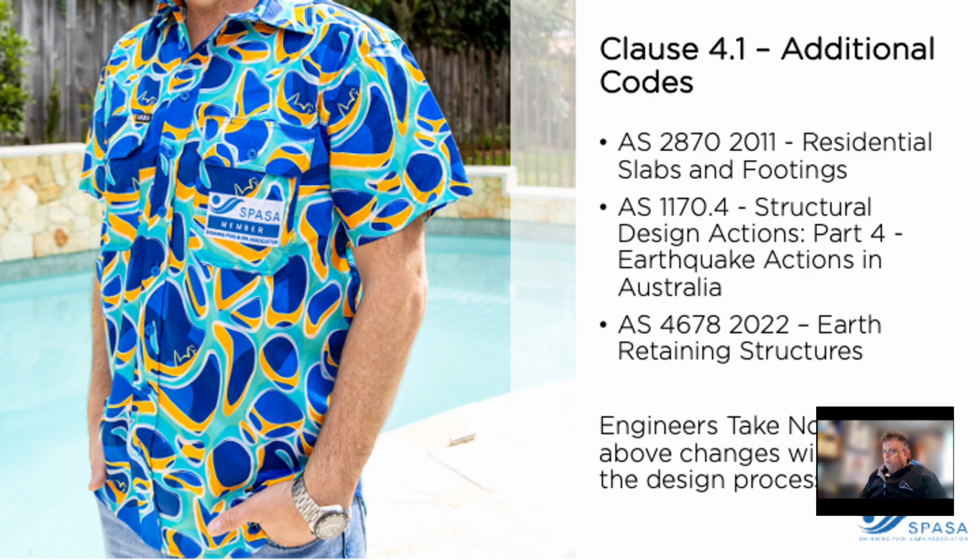And those soil reports will refer back to AS 2870, and the new code does refer to it. Therefore, it takes into consideration those site classifications in terms of the treatment and design of those pools. It also refers to structural design in terms of earthquake to ensure that we don't end up in a situation where during an earthquake a pool will fail.